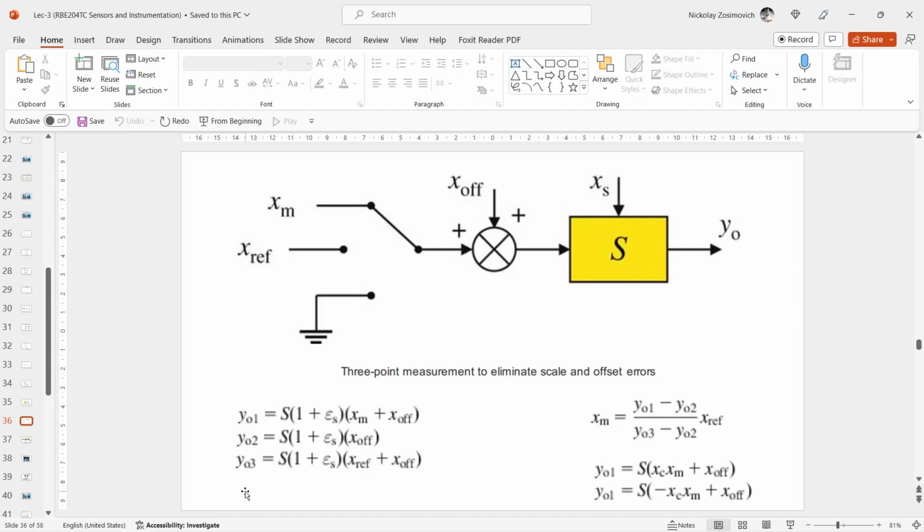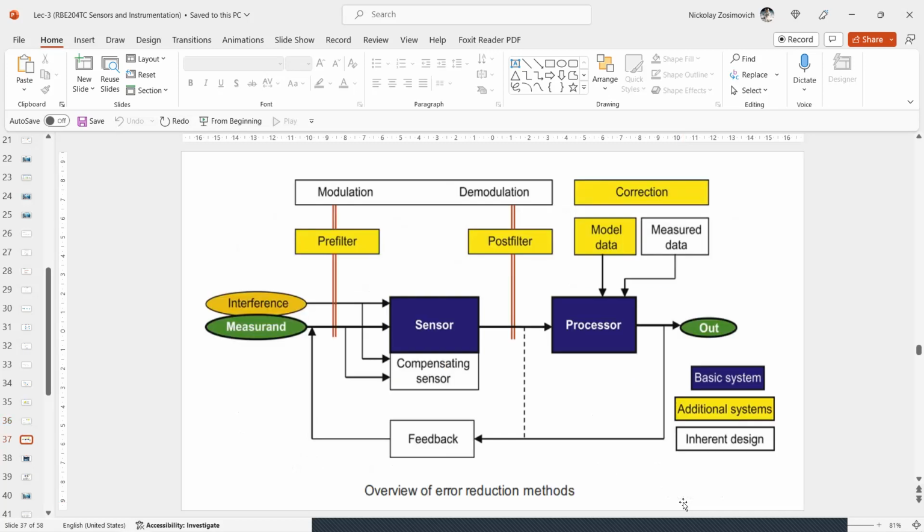Assuming the offset is independent of the bias, the offset reduction follows from this second equation. Here, XC in the bottom is the carrier signal, which is flipped between two sensitive measurements. Obviously, the difference between the two outputs is proportional to the input signal and offset independent.